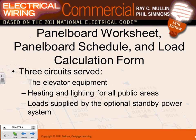Now, Jamie, my friend, you can imagine why the elevator has to be on the owner circuit: it serves the whole building with those 5 or 6 occupants in it. Then we have the heating and the lighting only for the public areas. All the hallways in a commercial building occupied by multiple occupants have to be fed from the house panel. Everybody understand where the house panel is, feeding all the common spaces?